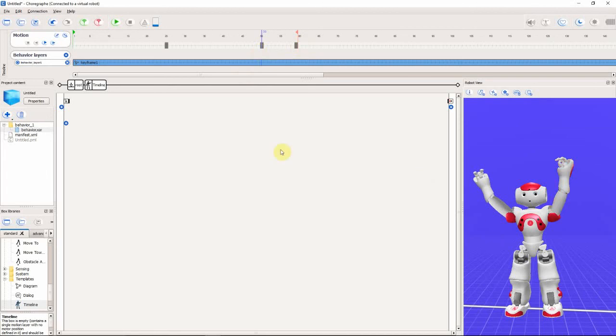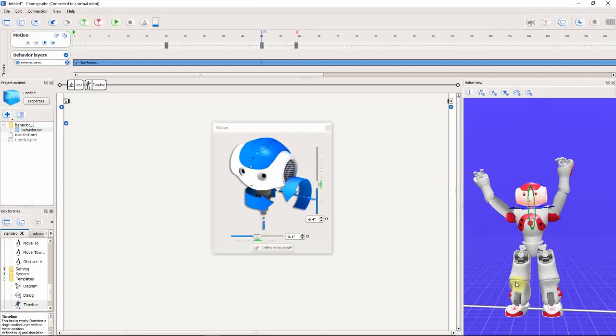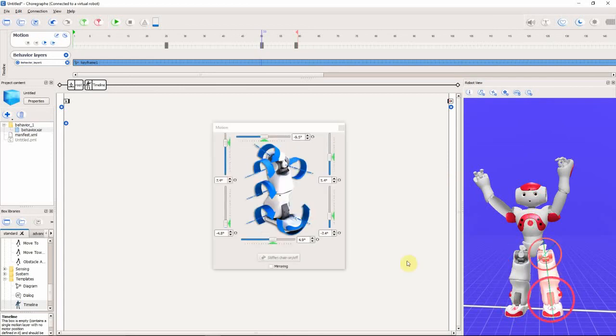This is the basic procedure for animating now. You can control both arms as I've shown you, also the head and the legs. When you start playing with the legs, you start running into things like balance of the robot, which need to be taken into consideration. The virtual robot does not simulate gravity, so please be aware that an animation that looks interesting and stable on the virtual robot does not necessarily mean it'll work on a physical robot.